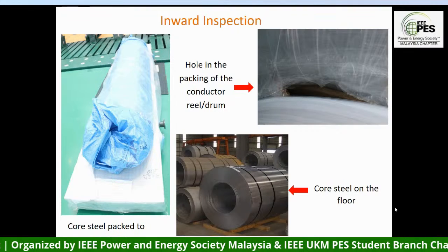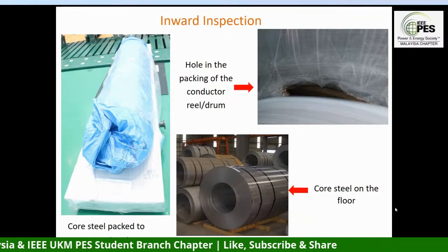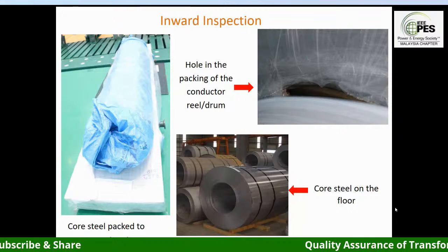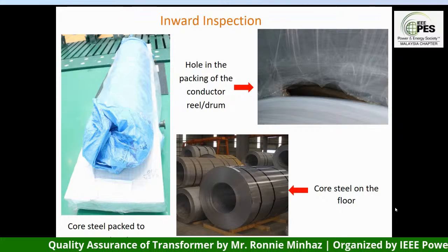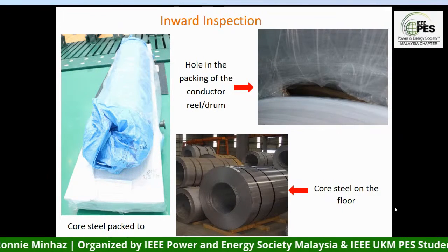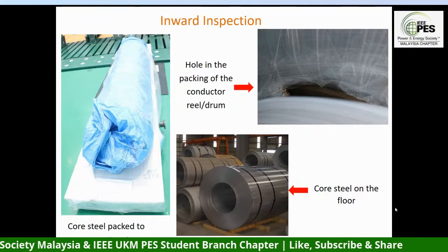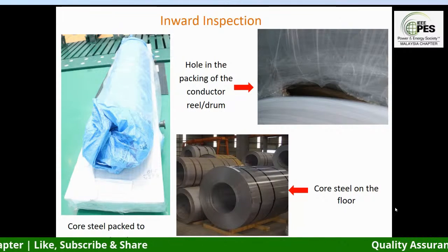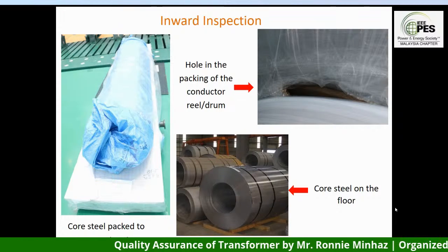The reason behind that, let's say for example, a transformer manufacturer is located in Malaysia, nearby the ocean, and Malaysia being in a region where it may rain during the monsoon season. Now, if this pre-cut steel is being shipped and exposed to the environment, and monsoon rain happens, it can pick up rainwater. Not only that, it can absorb moisture during the shipping process, and if it absorbs moisture, what will happen? The steel will rust.